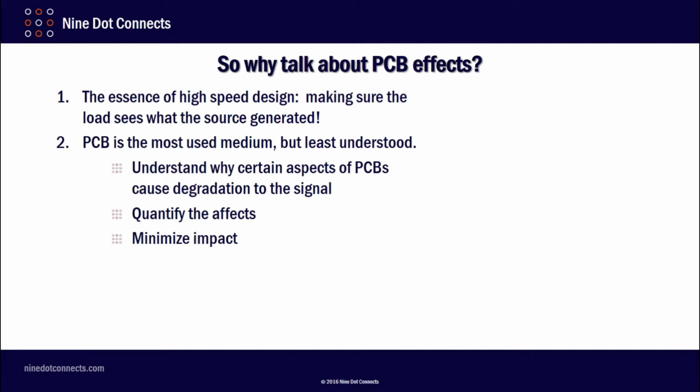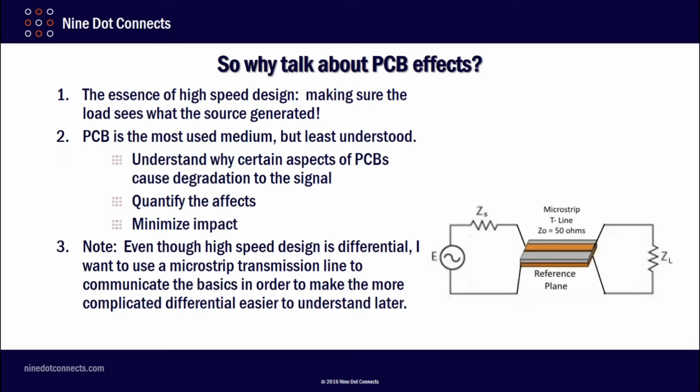The PCB is the most used medium, but it is often the least understood. So we want to understand why certain aspects of PCBs cause degradation to the signal. We want to quantify those effects and minimize the impact. The essence of high-speed design is making sure the load sees what the source generated.